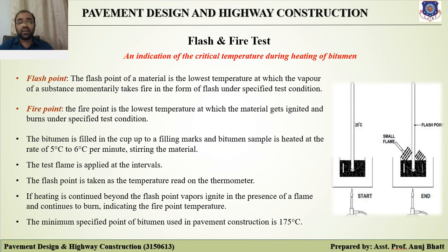The flash point of a material is the lowest temperature at which the vapor of the substance momentarily takes fire in the form of a flash under specified test conditions. And the fire point is the lowest temperature at which the material gets ignited and burns under specified test conditions. Now let's move on to the procedure of this particular test.